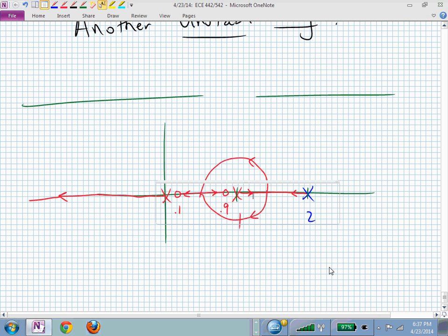Oh, so the question, I think, is really trying to confuse me, but the zeros are not directly related to the gains on your three different terms. They are a mix of the three different terms. You have a p term, an integral term, and a derivative term, and those are not directly related to the zero locations.